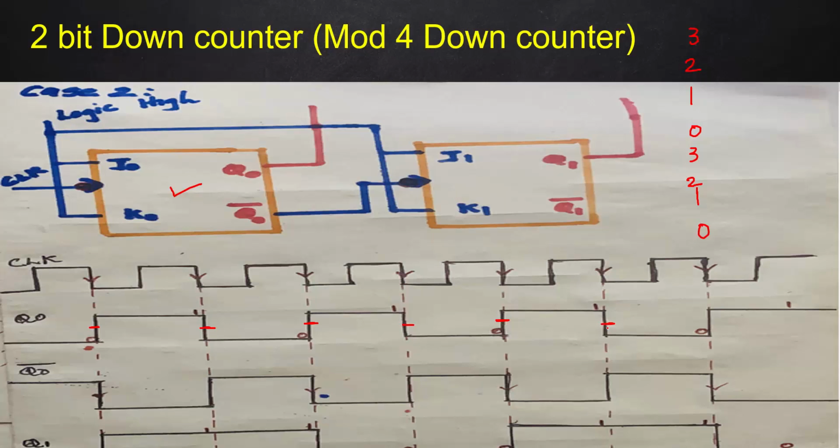See, here this Q is not going to trigger your next flip-flop. Instead, the Q bar output of the first is going to trigger. So Q0 is not directly going to trigger the next. You need to draw Q bar. What is Q bar? You need to draw the timing diagram of Q bar next.